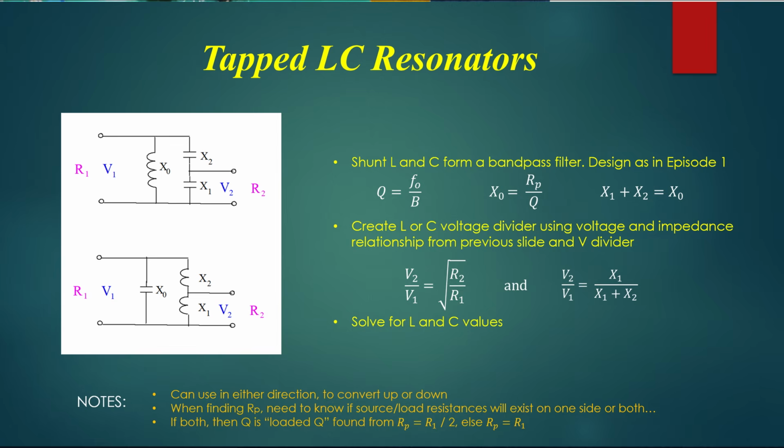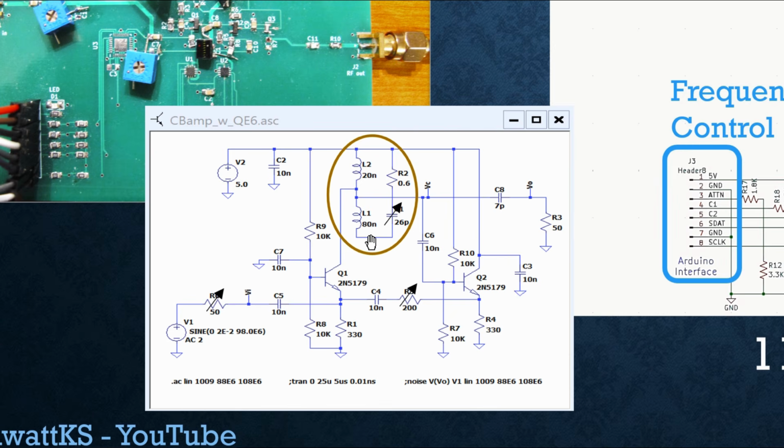What's going on here is at this node, down here at the bottom, if we look at the impedance from this node to ground, where's ground? Well, AC ground is up here. So from this node to up here, and if we don't have anything connected here or here, then based on the values and the frequency, we'd have about 6 k ohms from here to ground. But if we look at this as a matching network, as we did in Radio Design 101, and we say what's the impedance from this node to AC ground, it would be about 250 ohms.